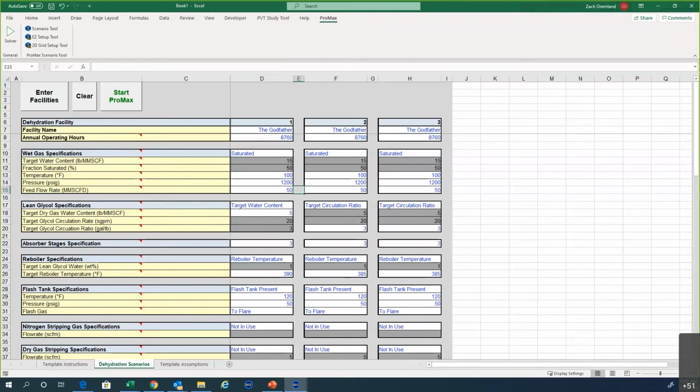That's exactly right, Bill. So Bill mentioned that the saturator has a solver depending on the parameters you enter. So Bill, you must be familiar with the tool a little bit. That's exactly right. Based on these inputs that you're entering for determining how much water is in your wet gas, that's going to dictate how this solver operates, and it will force whatever water content you define or force it to be fully saturated with water.